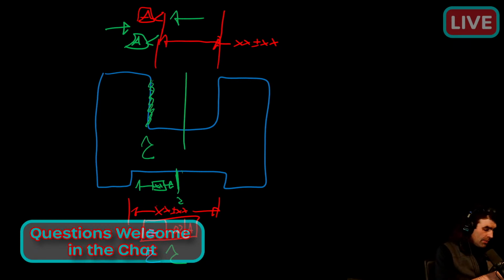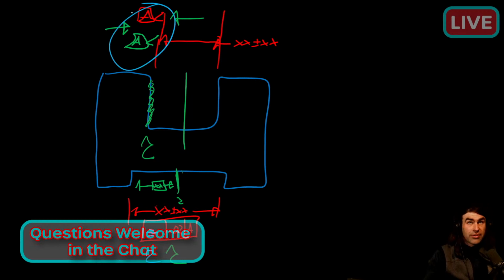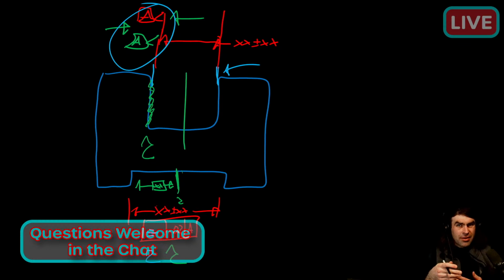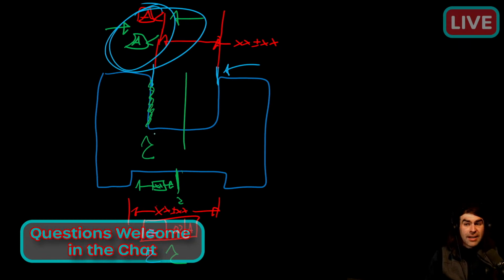And it's probably the same kind of people that make mistakes with this datum feature symbol. It is really, really important to get that right. I know it seems nitpicky, and a lot of things are nitpicky with drawings. If I have a student that runs their extension lines into the part, I've got to say something. I can't just let that go. But I wouldn't reject a part, run up the total of a quote, or say this drawing is completely wrong. That's just like a note. I typically wouldn't take points for that. But if you screw up the datum feature symbol, you're really setting yourself up for problems in the future.